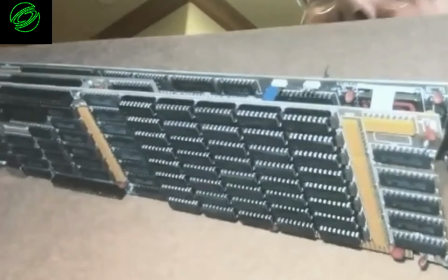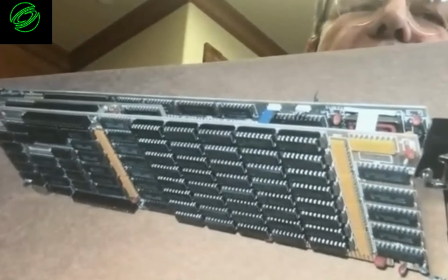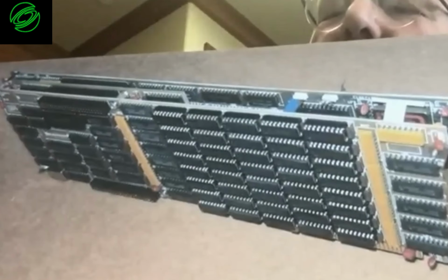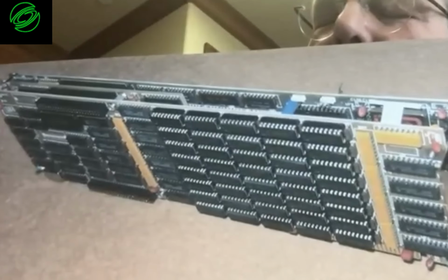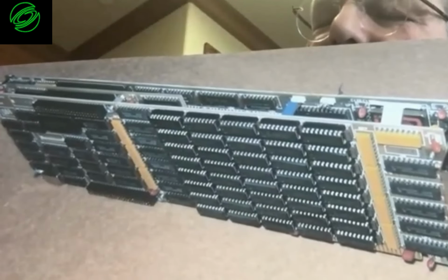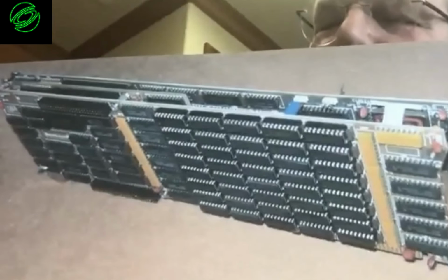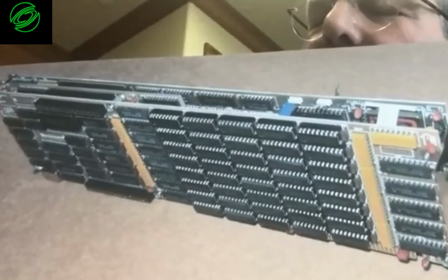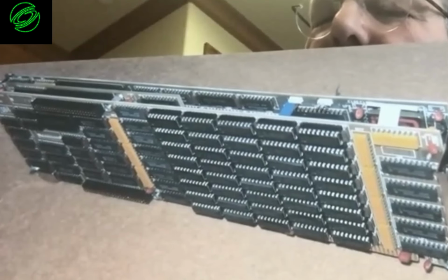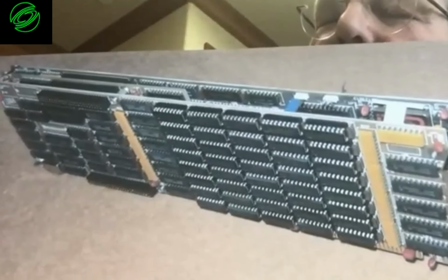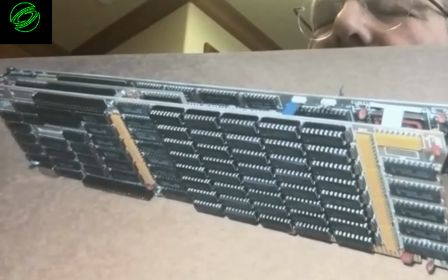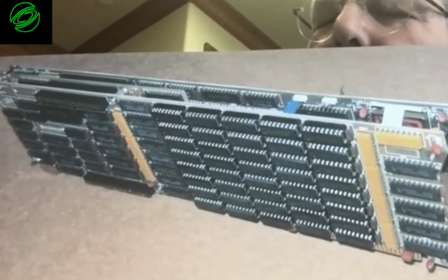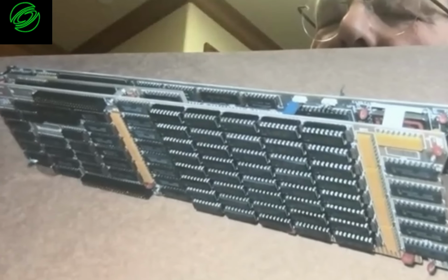I'm going to do this old school because I'm on an iPad, but this is the IBM PGA board, which is the first accelerated graphics card in the PC industry. It's a 3-board, 2-slot system. The tiny board in between is a CGA emulator, and it actually has an 8088 as a processor on it. What you see on the front is all the memory related to the color graphics. The other card that was in the PC at the time was the MDA, the monochrome display adapter.